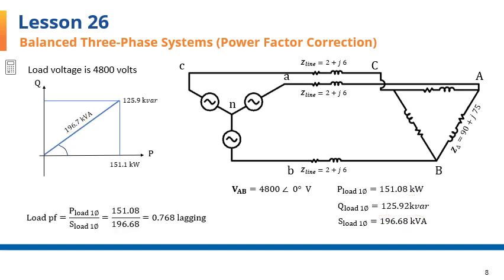And here is that fraction, real power of the load for single phase divided by the apparent power of the load, again for the single phase. And the power factor of the load without the capacitors comes to 0.768 lagging.